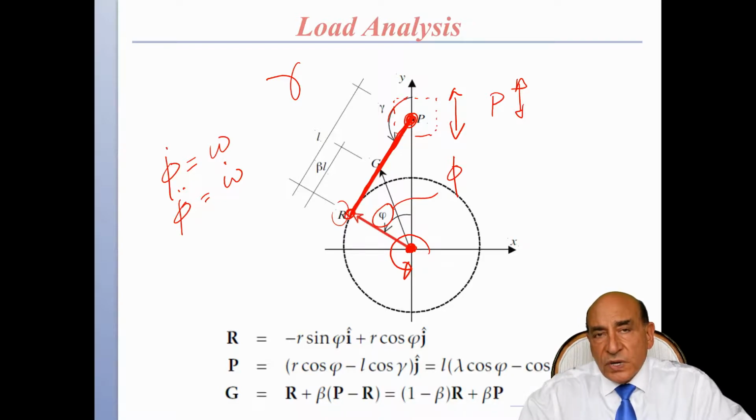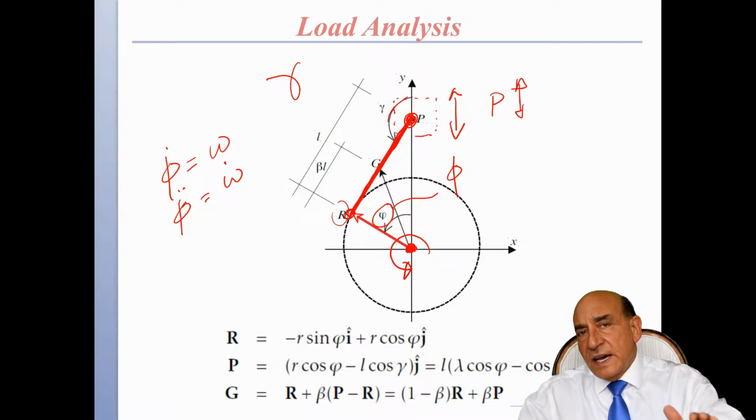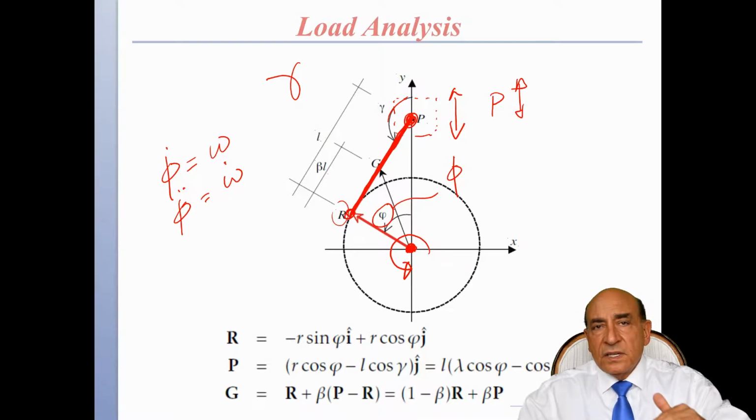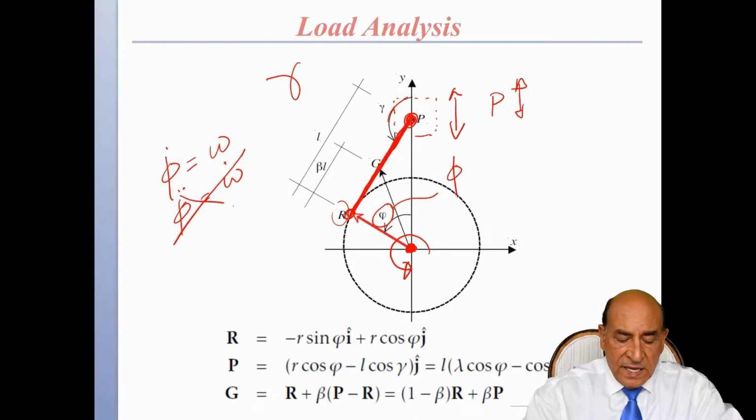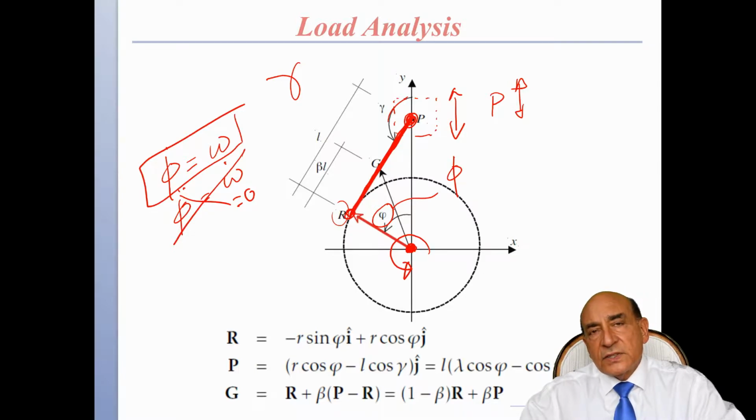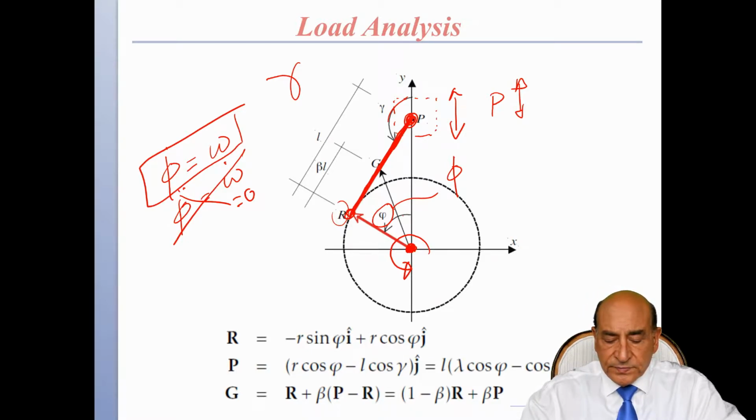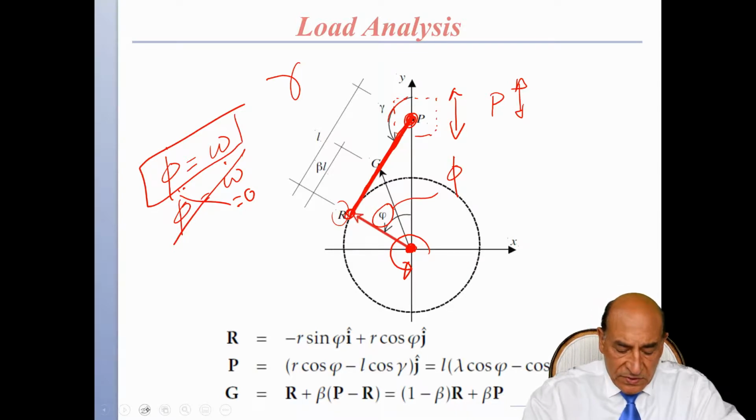Now, for our design for this rod, we're going to look for steady motion. So we're going to design it at the peak conditions, which is the peak torque and RPM combination, and assume that it's going steady at that rate. So there's no acceleration. And in this case, omega dot is equal to 0. So we're going to design it for phi dot equals omega equals a given RPM, and that will be included into the analysis.